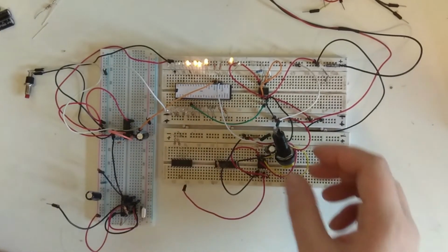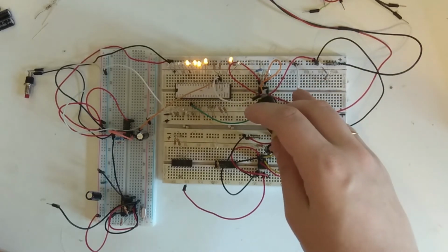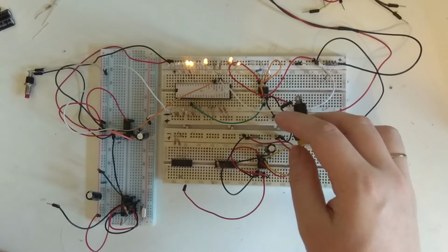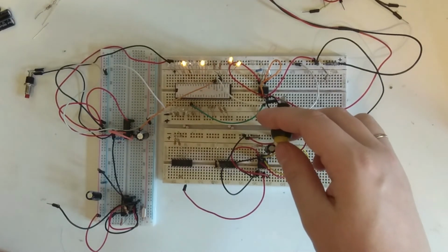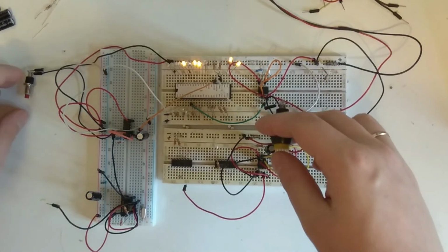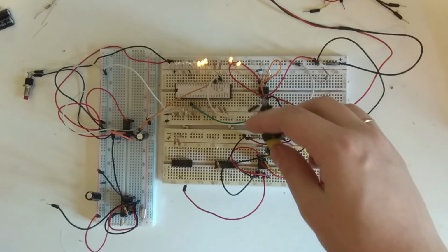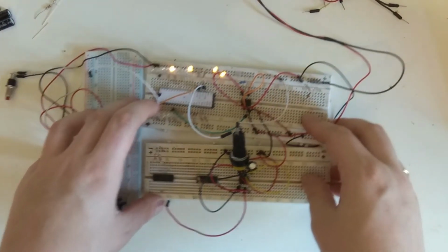It would basically just sit there doing nothing, and instead of the circuitry, I can just put in a switch like this with a pull-up. And this seems, even with no debouncing, to work much more reliably, which is odd enough. So yeah, that's my little prototyping setup here.